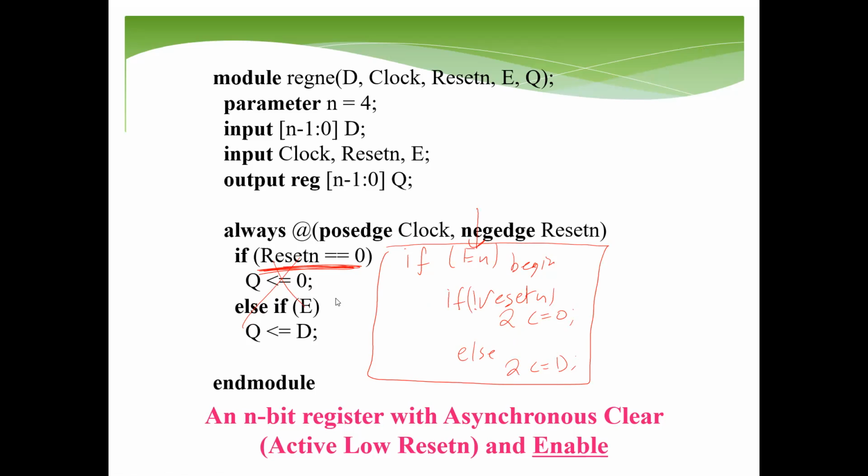A student asks about E being synchronous. Yes, E here is considered a synchronous signal. That's fine. If you want E asynchronous, you have to come back to the sensitivity list. But E doesn't have to be an asynchronous signal.